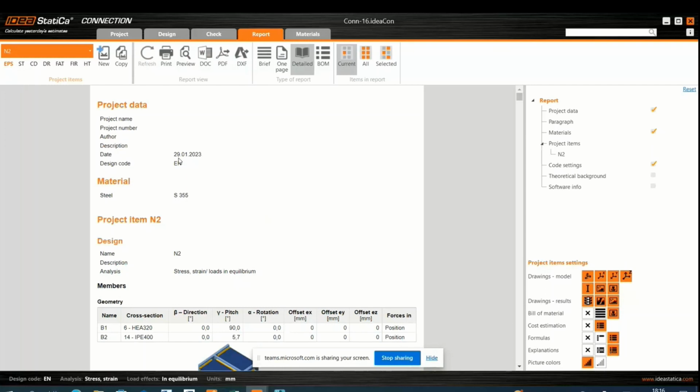Okay. You can use the connections and the checks for the connections that are inside SCIA, but I'm not sure that Tekla recognizes everything that you will export from SCIA, because Tekla has a problem with haunches.